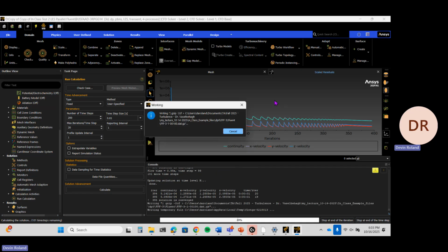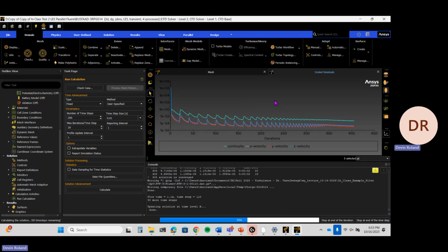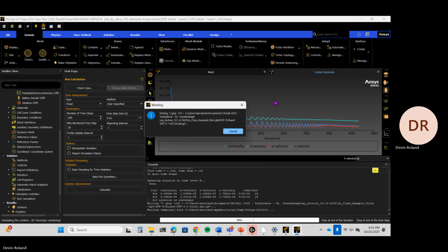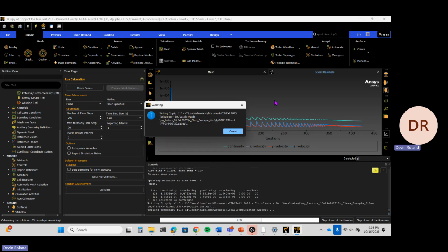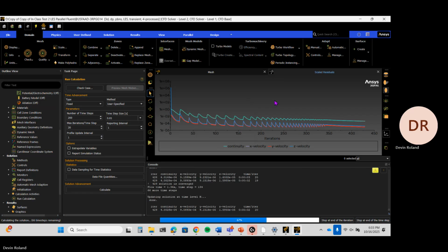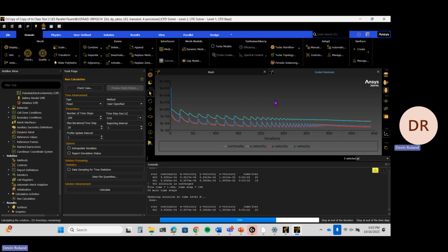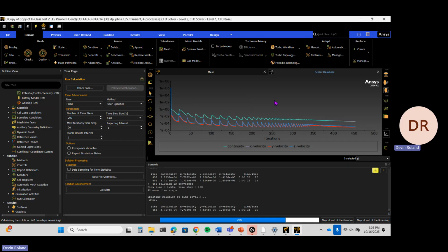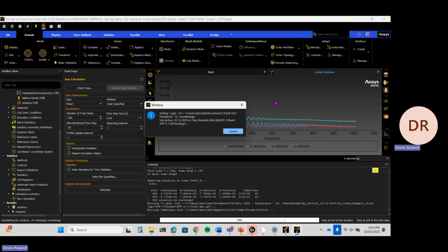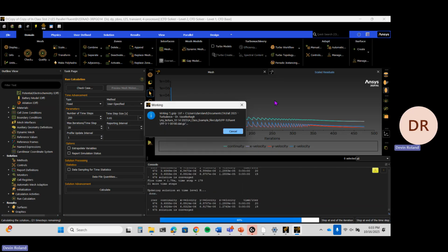But then if you had a small vortice like that, that's not resolved, because it's contained in one grid cell. So the general rule of thumb is that you want your grid to be small enough, say like that size, so that you can resolve eddies this size, eddies that size, eddies this size, and then only have some eddies that are smaller, that are sub-grid scale.